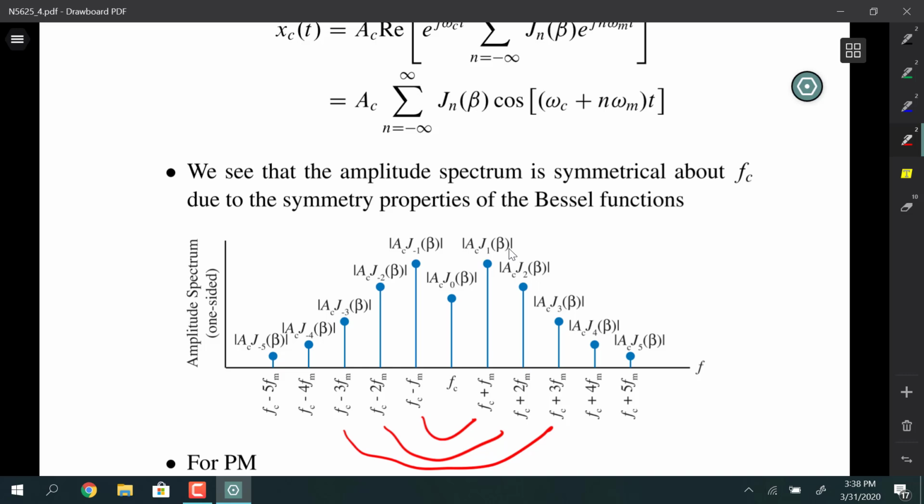And just to pause here for a second, if we were back on double sideband and we were modulating the carrier with just a message at frequency FM, that would be this inner rectangle. The bandwidth there is 2 times FM.